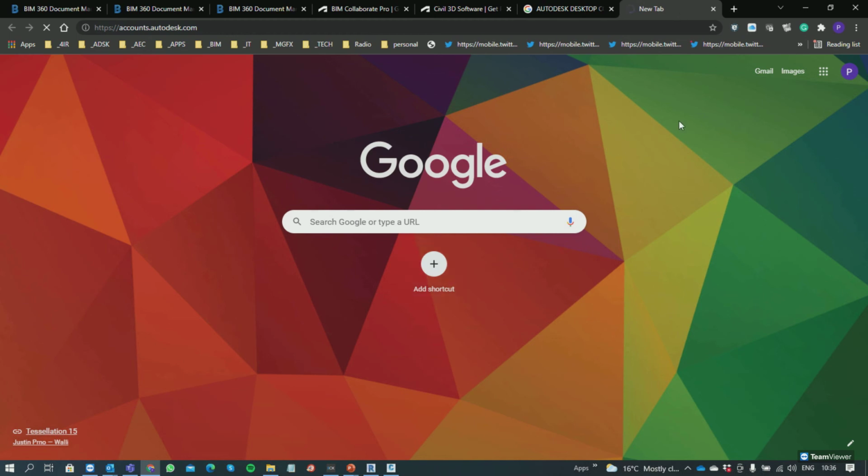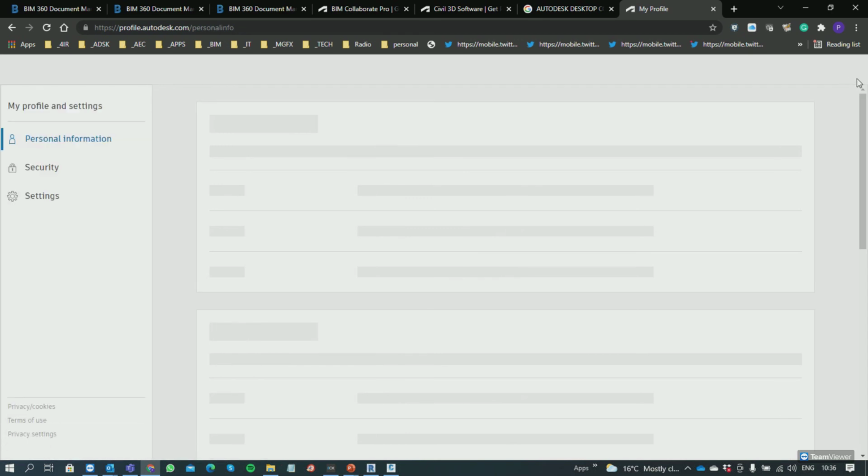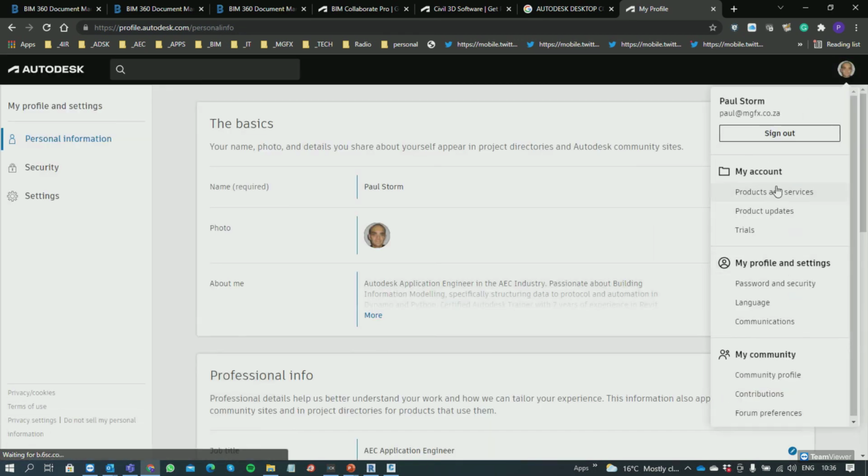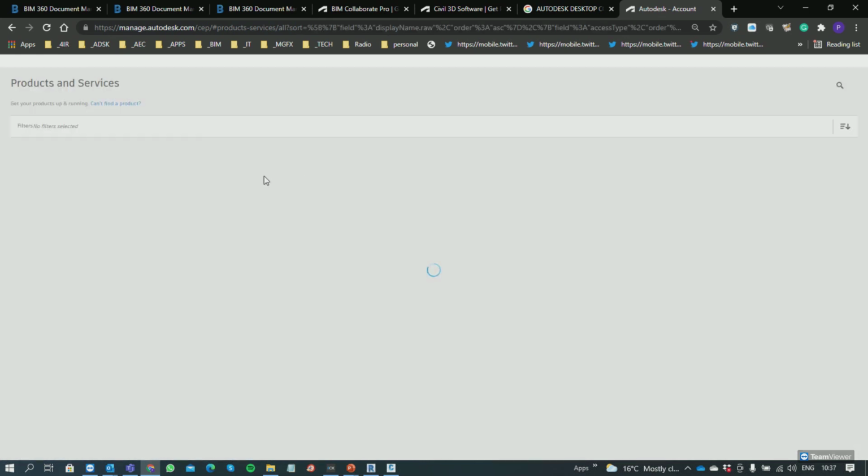And you would simply go to your Civil 3D platform in your account, download and install that app. We can show you how to do that quickly. And then once you've installed that app, you'll be able to use the export of a coordinate system. In 2022, that's already been built into the software, so you don't have to worry about installing anything. And so that would be a very easy thing to do.